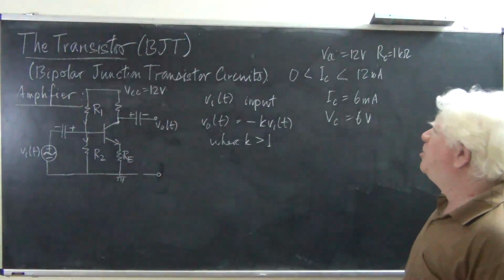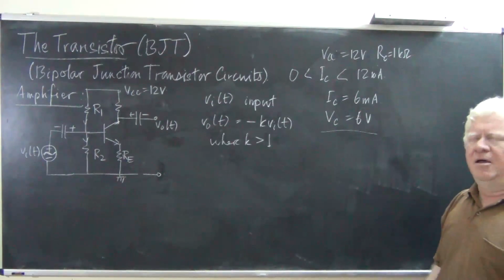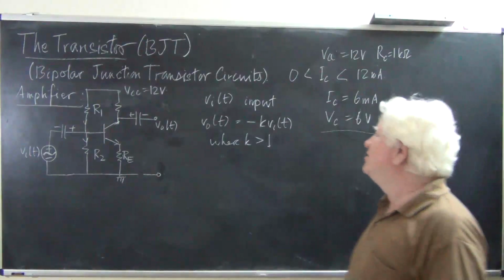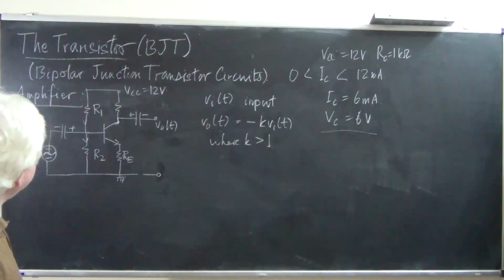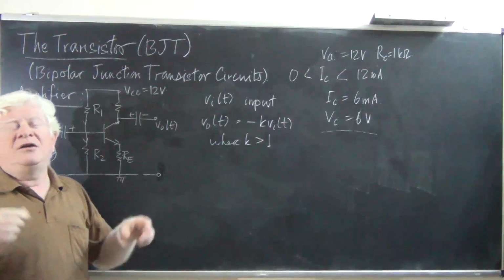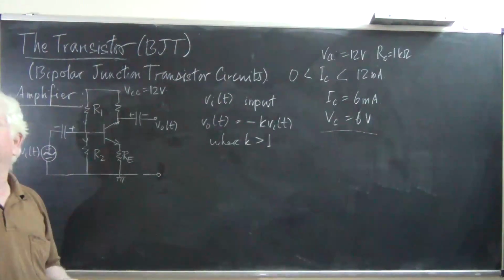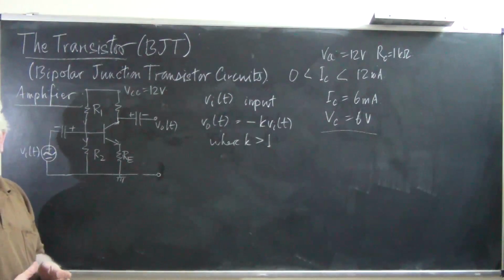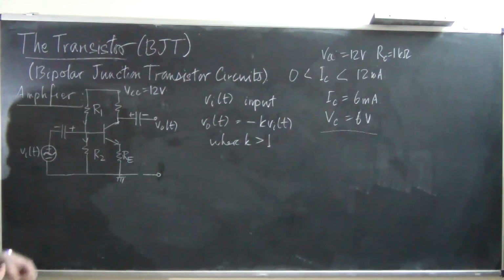Now once this is done, the transistor is ready to be used as an amplifier. Now let's see what things are left to be done and discussed. These bias currents and voltages are DC quantities. We don't want them to enter the load and get modified by the amount of loading that occurs, or to get into the input source.